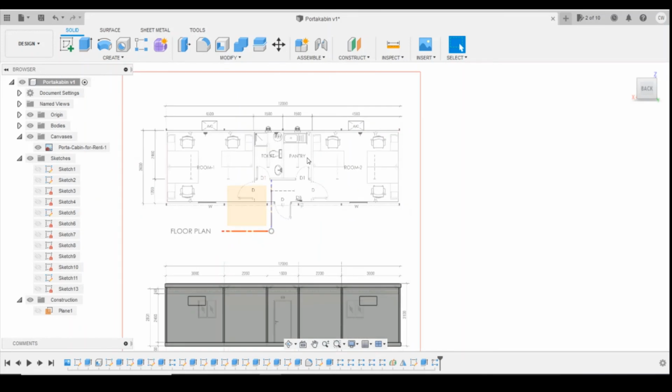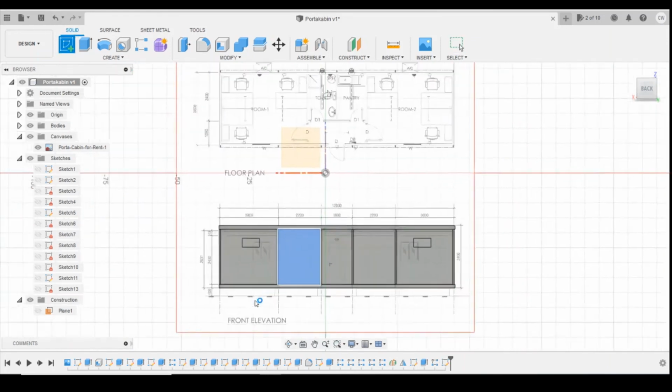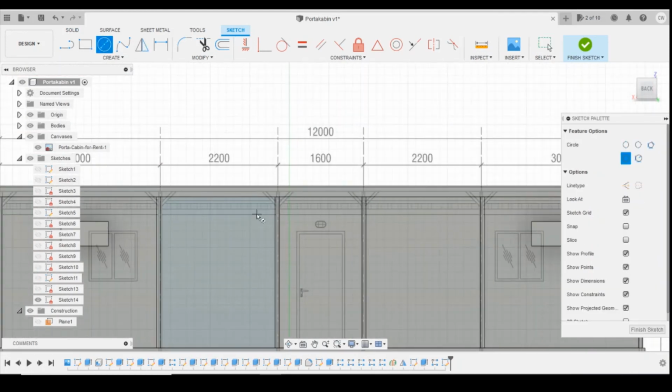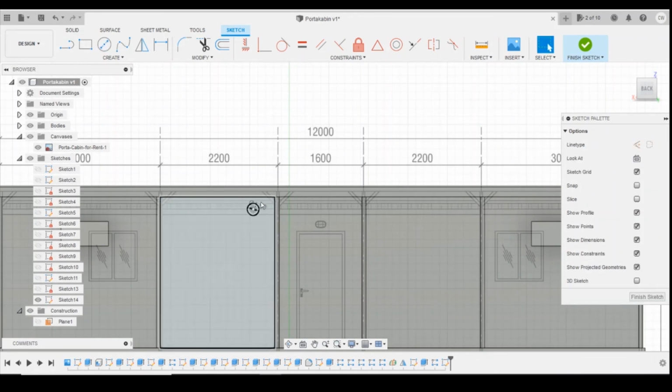So the next thing we're looking at is the two vents that are going on the back, and I'm going to put them either side of these two center pillars here. So we'll create a sketch on that surface using that center point circle. I'm going to draw a circle, 1.5mm, and then we'll define its height, and its position relative to that post next to it.